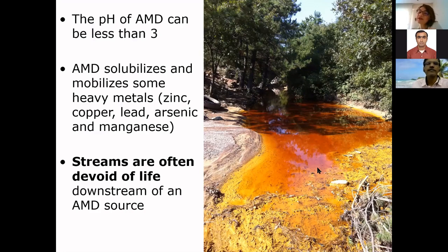But for this area, I think electrokinetic remediation is not good because the area is very big and tailings are very, because electrokinetic is suitable for the finer material like sand, silt, clay, like that, but tailings are coarse-grained materials. Okay. I think the best option is phytoremediation in this area.